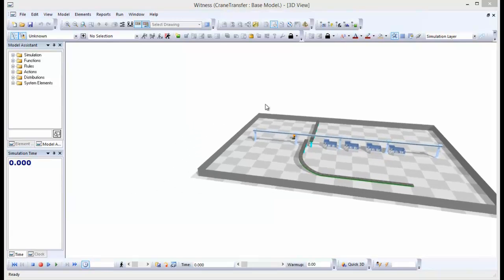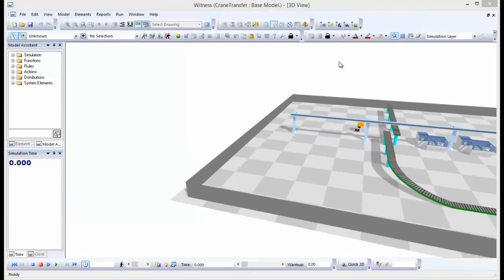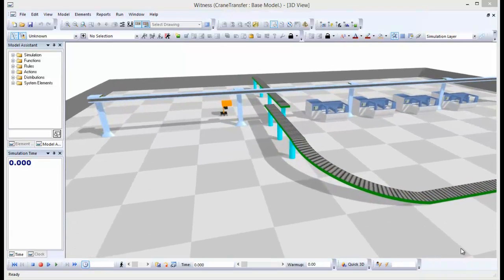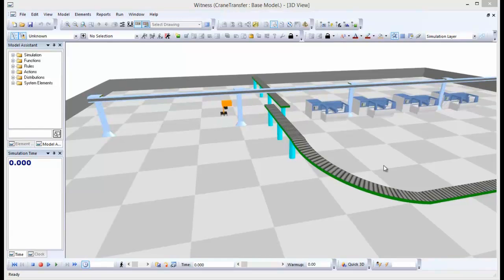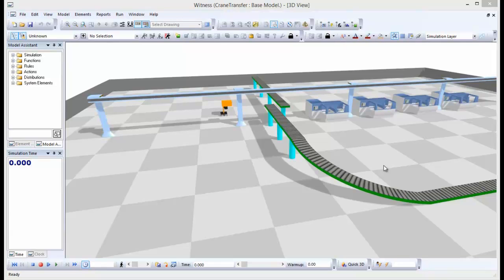And another thing that's well worth knowing about the 3D view is that we have the ability to turn the shadows on and off as well. And we simply do that with a Control S command to turn the shadows off and then back on again. Very useful if you're inside buildings which cast deep shadows almost everywhere. It's possible then to just turn them off so you get a brighter, lighter view. It also slightly speeds up very, very large models to not be processing shadows, so that can help with the performance of the flight around as well.